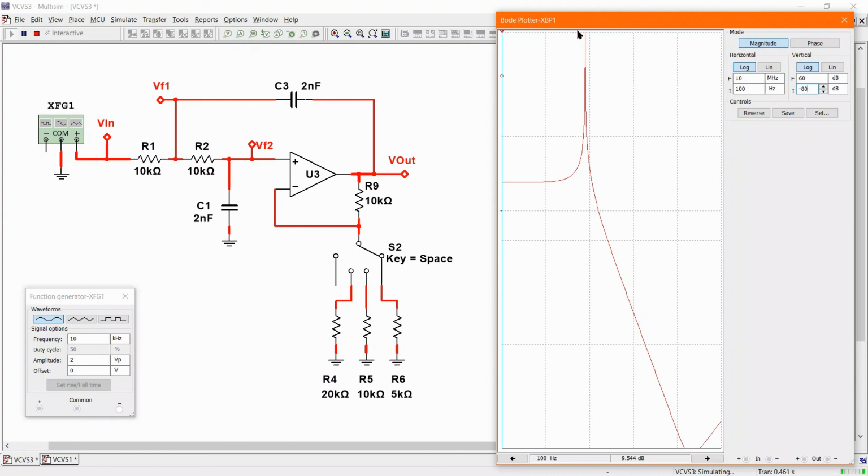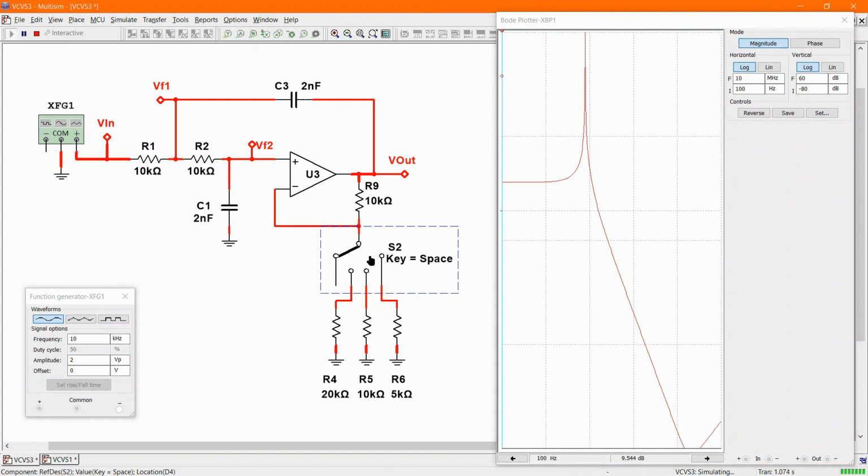And there's a problem with having an output that peaks so much here, because if there's any kind of a little bit of an oscillation here, then what can happen? It can start to oscillate at this frequency, and it doesn't matter what the input is. Basically, the output becomes so large that it overpowers the input, and the only thing you see is a frequency out at this value here. So by playing with the gain factors, we can also modify the characteristics of the low-pass filter.